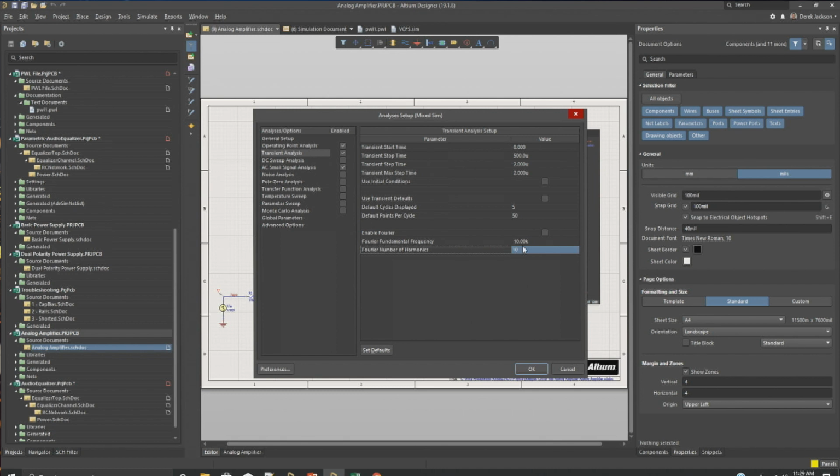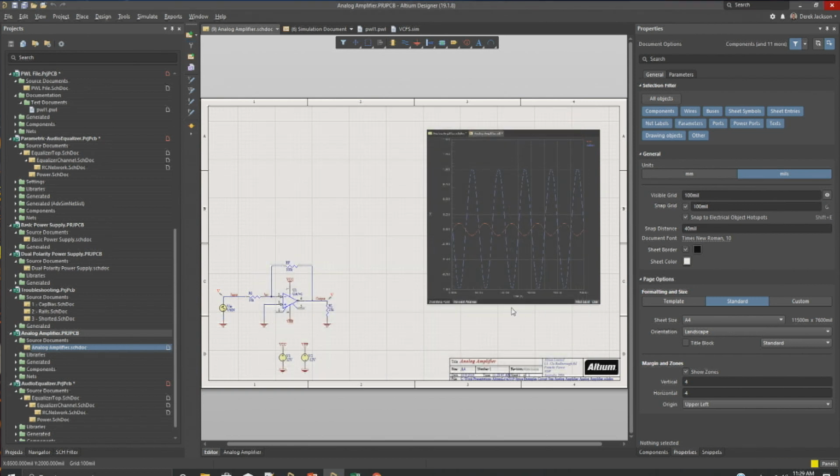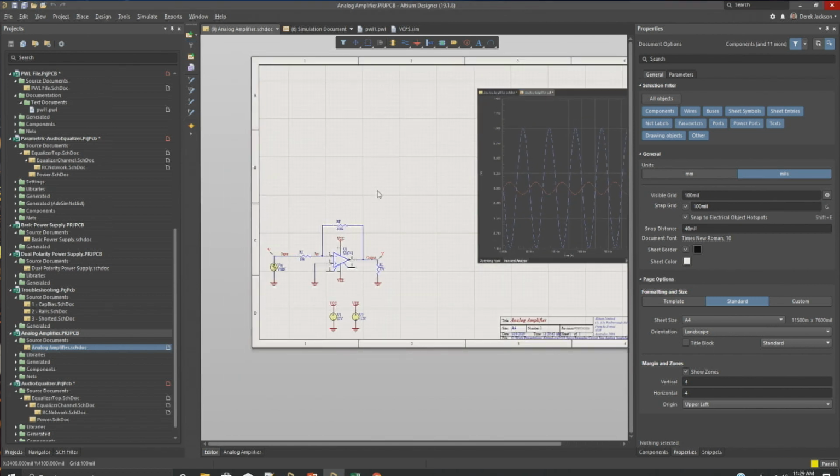It just calculates the main fundamental frequency, and then calculates the number of harmonics on either side. So it's limited to what Spice does. There might be some more advanced calculations in some other tools. One thing that is nice is that if you have everything set up in here, you can export out a netlist, and that can usually be loaded into another Spice 3 simulation tool, or even LTSpice, which is really popular. Even though it's called XSpice, it's really Spice 3. We do have XSpice models in there, but it's primarily Spice 3 driven.